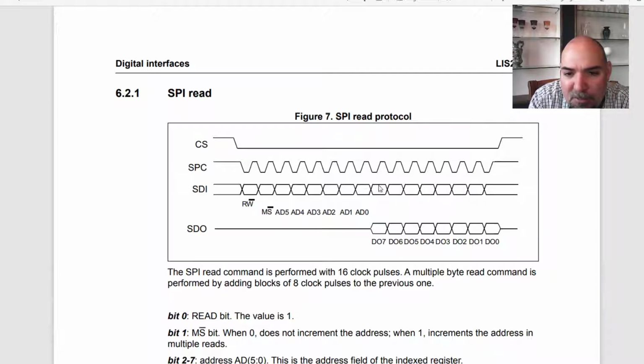These are just clock signals for that shift register. It's still going to exchange values, but it doesn't matter what we put here. And in SPI implementations, a lot of times you'll see that as a dummy byte, dummy values going out that don't matter because we did a read. When we do a read, we're reading what came back, ignoring what went out.